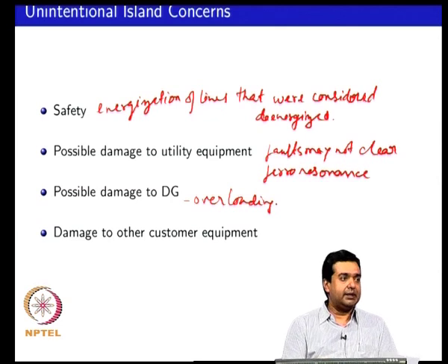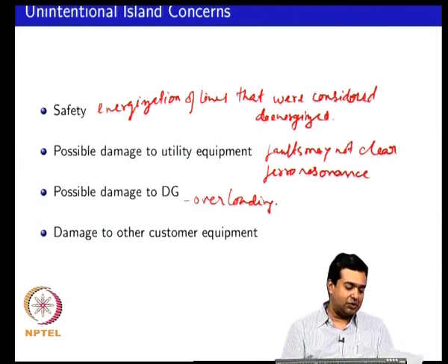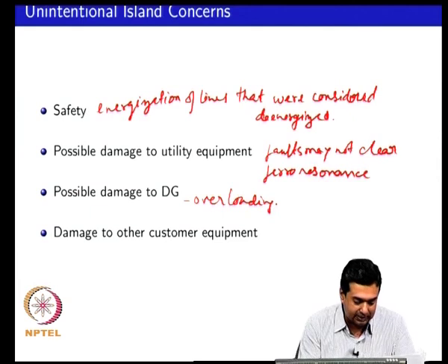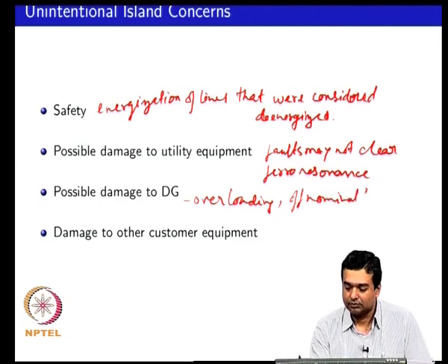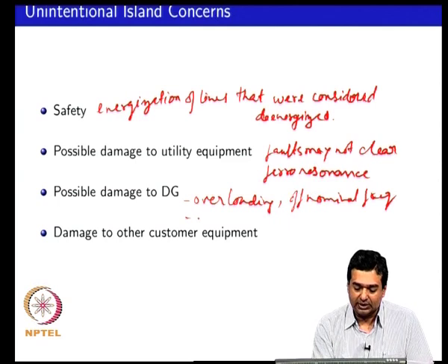You can also damage the distributed generation source itself, because you can have overloading, because you are trying to carry a wider set of loads of the entire feeder. Your frequencies might drift outside nominal values. Also, a possibility is out of phase reclosing.